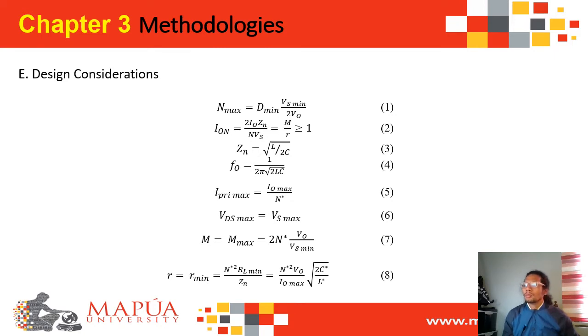The minimum conversion frequency occurs at low line and full load. Equation 7 shows the relationship between the minimum conversion frequency and the load of this half bridge converter. The maximum value of the normalized load resistance at which zero voltage switching is achieved is given by equation 9, and the minimum regulated output current is determined by the Rmax of equation 10. It occurs at the maximum conversion frequency from equation 11.